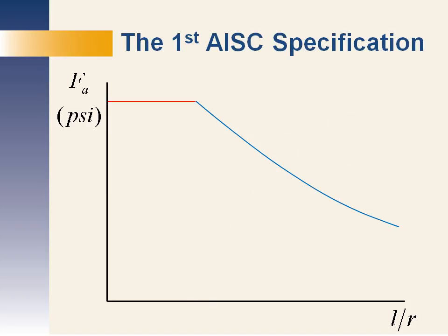Now, in the era of this type of curve, consideration of the combination of stresses was required, but the basis of the requirement was fairly crude. It simply said, members subject to both direct and bending stresses shall be so proportioned that the greatest combined stress shall not exceed the allowed limits.